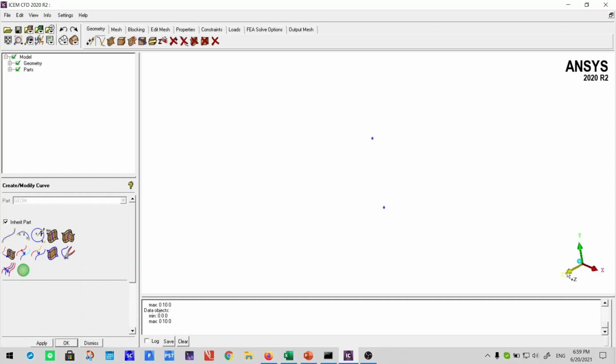So the best way is to switch to this Z plane or XY plane, and I'm gonna select this as a center point. This is the second, the first point over the circumference, and any other point in this XYZ plane. If you click, the circle will be generated. Doesn't matter where you click the third point. The third point may be clicked anywhere.